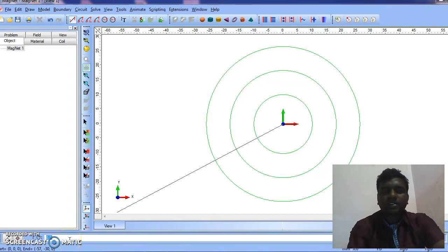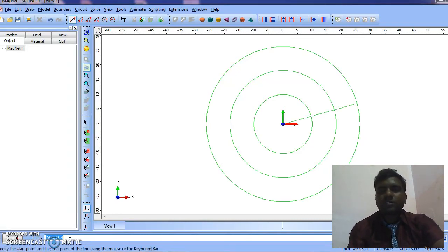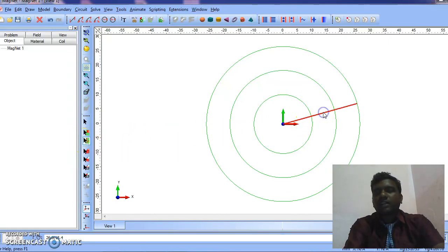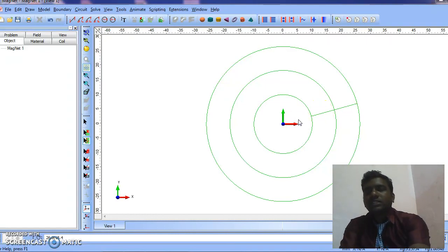Before that we have to initiate it. So just initiate it and then it is 26.3 comma theta. The theta value is the rotor pole arc. I take it as 30.8, which is divided by 2, so that we get 15.4. So we get a line over here. Just escape, and this is the tool to select the lines. I select it, and this is to separate the continuous line. Now we can see the discontinuity over this line by selecting. So just delete it.